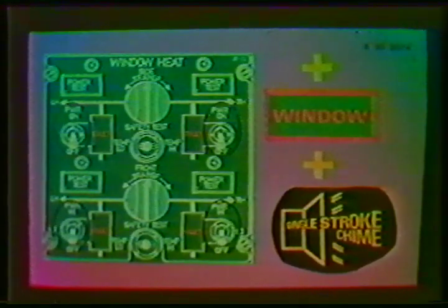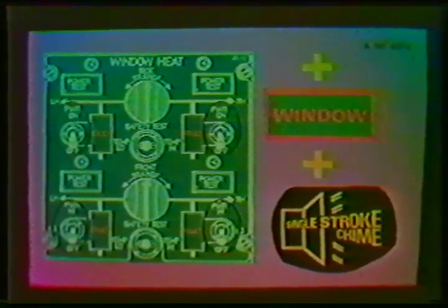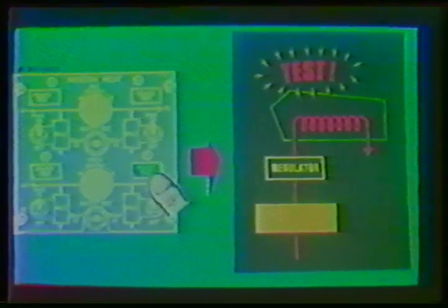The window heat must be selected on at all times. If it is not, the warnings will be energized. A test system allows a windshield heat system to be tested for continuity. This can be accomplished by depressing the power test light. With the respective power switch on, the blue light will illuminate when pressed to provide a functional check of the system. The test will stop automatically after 10 seconds to avoid overheating. The light will extinguish.